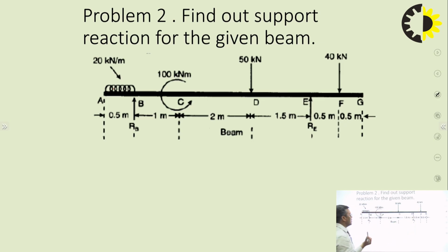Very good, we can write the equations clearly. Which type of force system is it? It is a non-concurrent coplanar force system. All the forces are lying in the same plane, so this is a coplanar force system. For a two-dimensional force analysis, again we have to deal with three equations. Sigma Fx equal to 0.